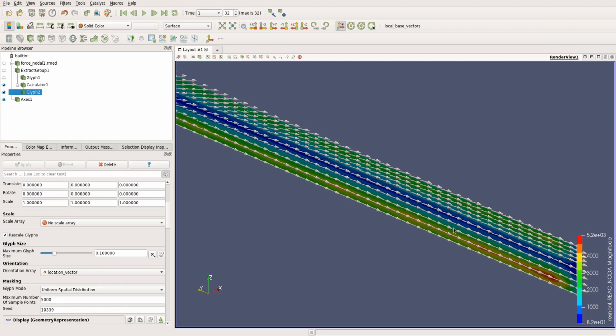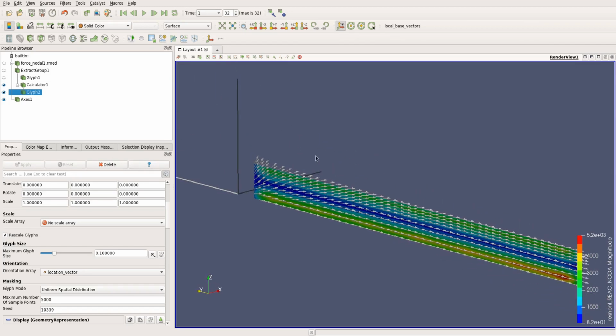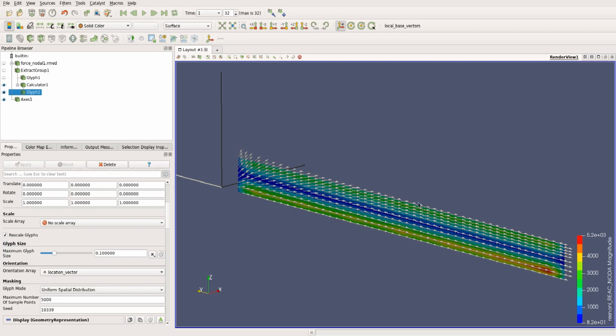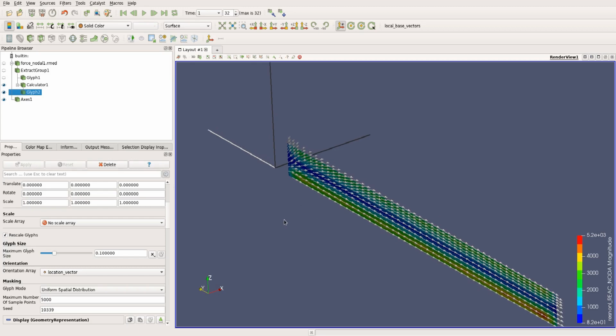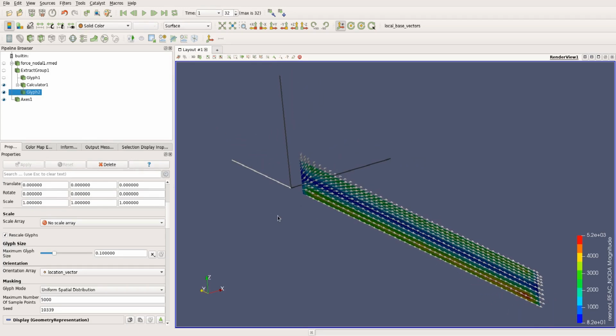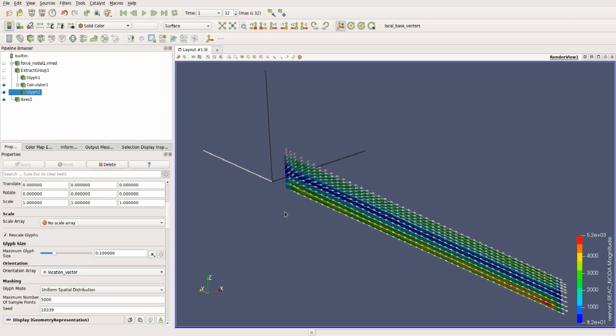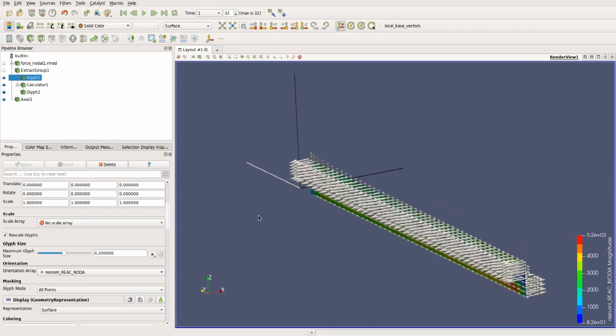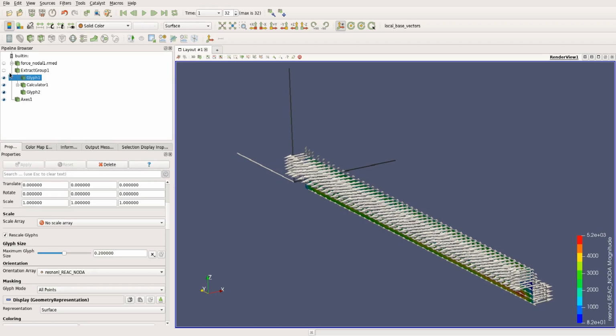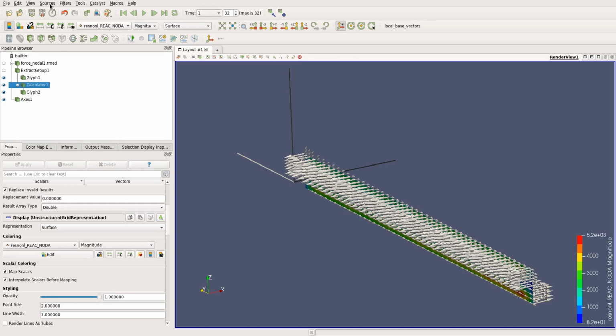Okay, and the change orientation with the point. So that's how we get the position vectors. And now it's time to calculate the torque. So for each point we want to calculate the cross product of the position vector and the nodal reaction forces. And what we now do is select this one and again put a calculator, and the calculator